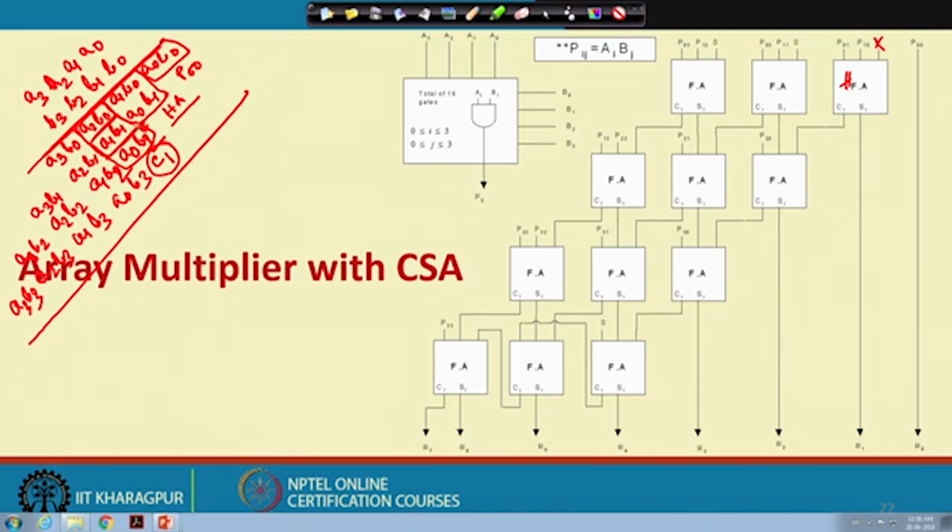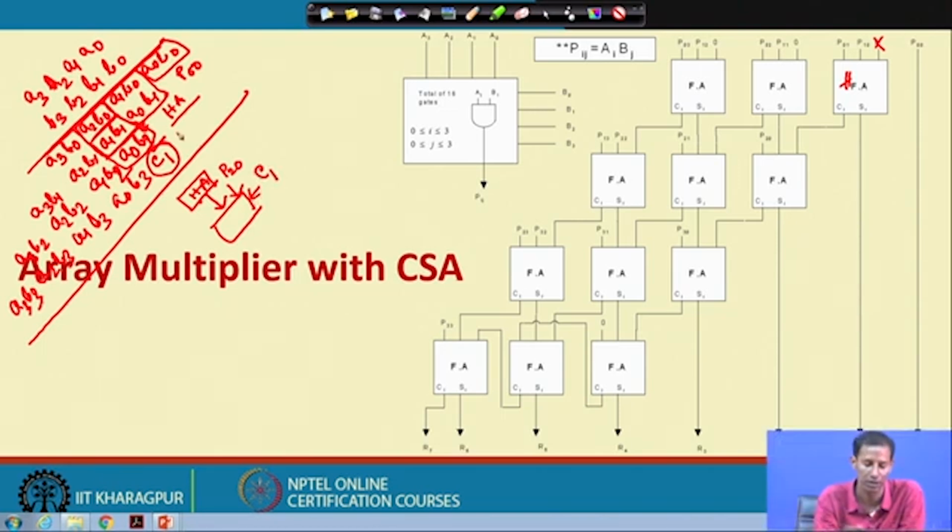So, I add A1 B1 and A0 B2 first using one half adder. Then from this half adder circuit, that will be added with A2 B0, that is P20, along with the corresponding C1, which is the carry from the previous stage. Okay. So, this is one full adder cell and it will produce the corresponding S2.